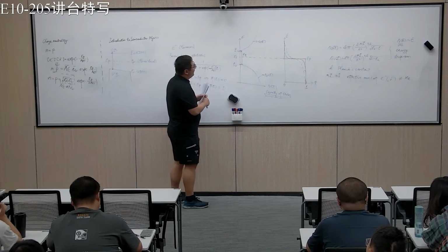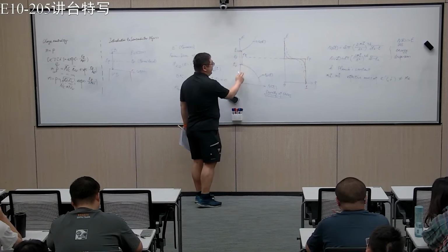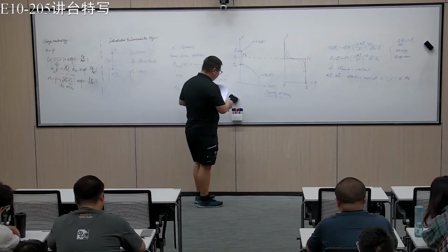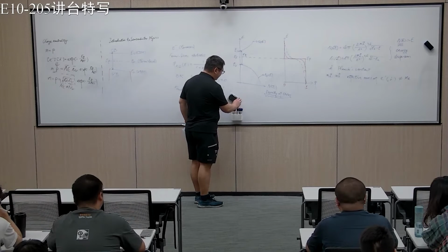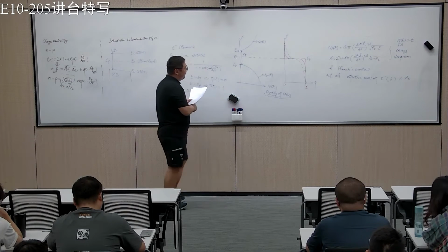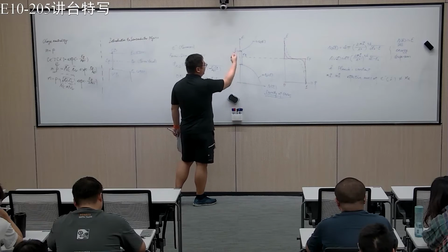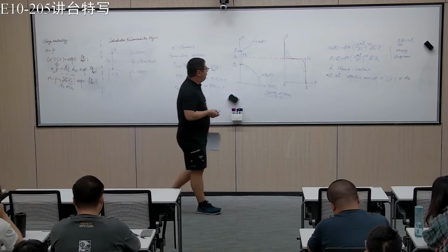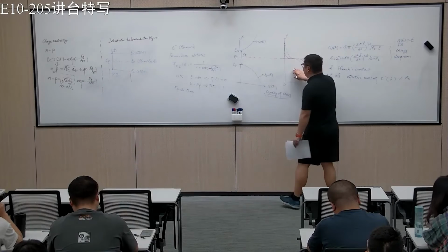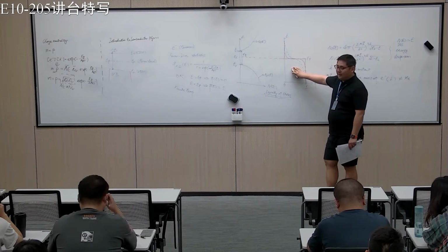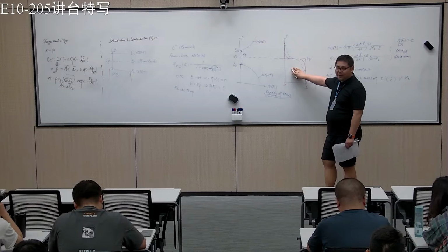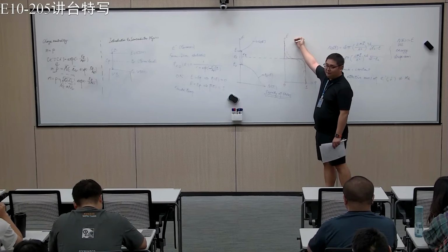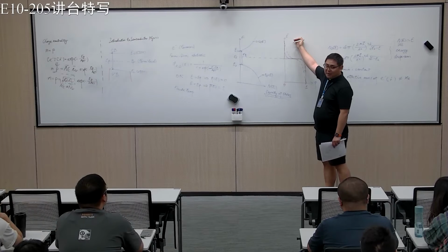So we know that we have states here, we have states here, right? So the goal is to see how many electrons we have and how many holes we have, because holes can only be here, electrons can only be up there, right? So let's say again at absolute 0 Kelvin, we know that everything above the Fermi level will be empty, right?